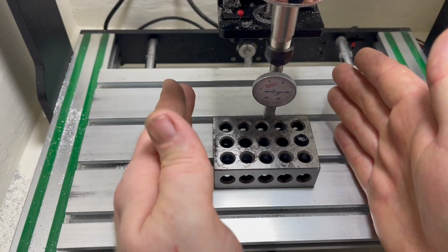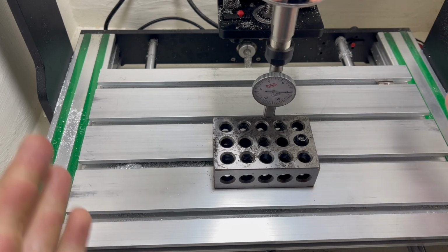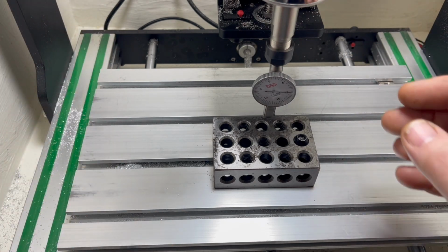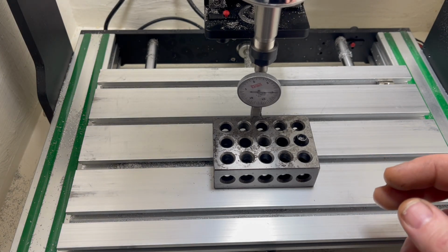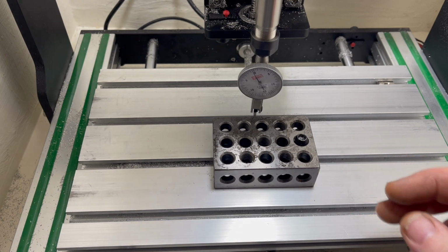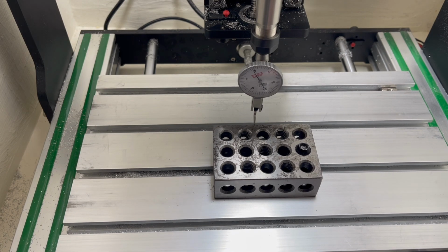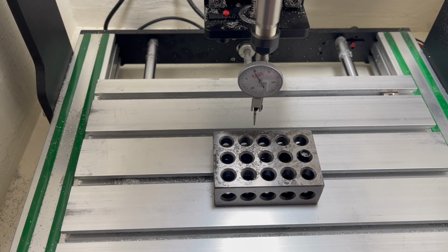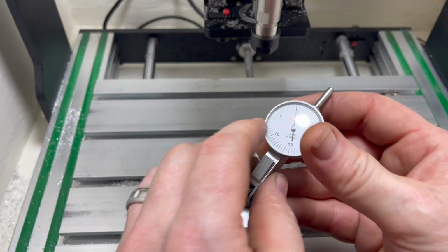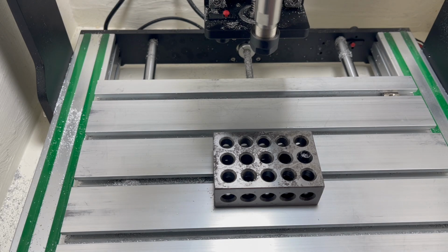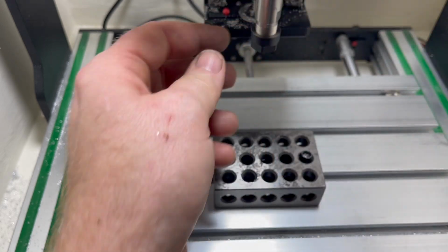I have this positioned just right so that it's parallel and perpendicular to the travel of this unit. Okay. Now I'm going to get that out of the way. Need to loosen this. I just have the machine turned off so I can turn these by hand. Once it's on, the stepper motors lock into place. This is just a 4 millimeter shaft, so you need a 4 millimeter collet. They're usually 3/8 or 4 millimeter for those indicators.